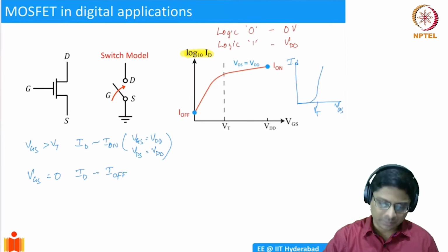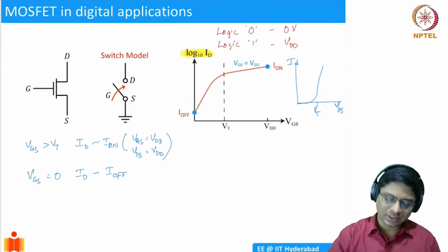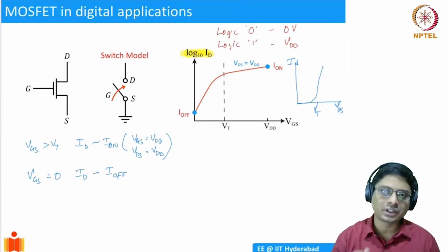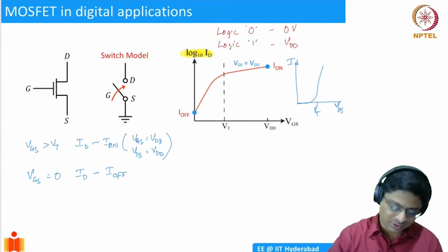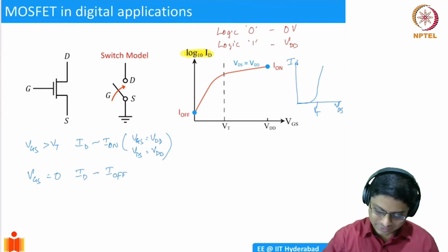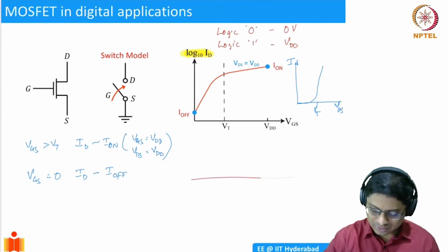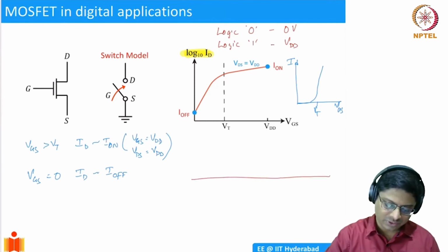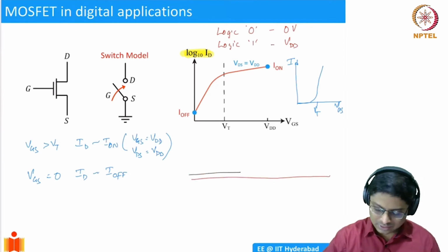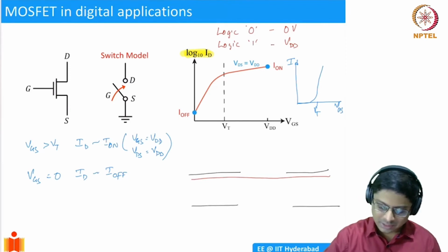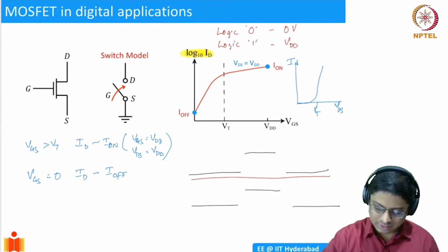And it is not quite surprising if you think about it. What is the reason for how the gate is actually controlling the drain current? Well, you should always go back and remember this physical picture wherein you have a Fermi level which is constant, and then you have the source and then the drain, and in between you have the channel, right? So we saw that there was a barrier forming here.